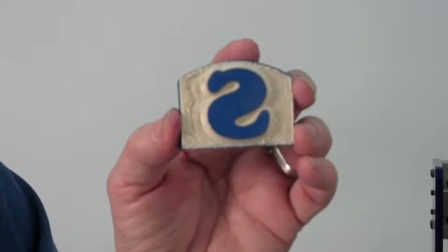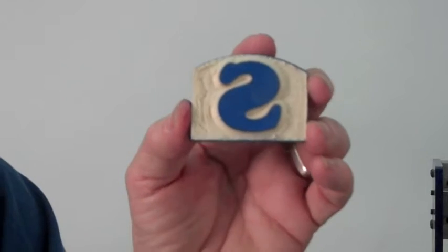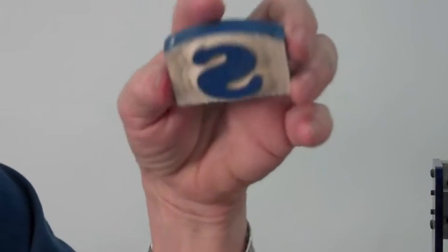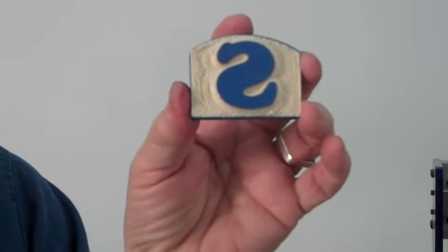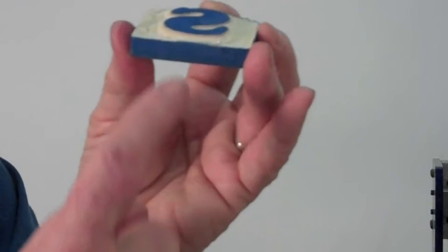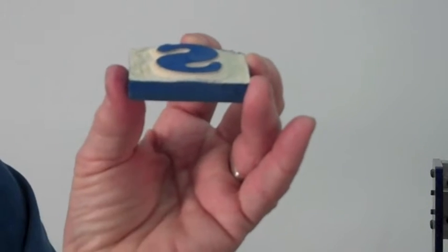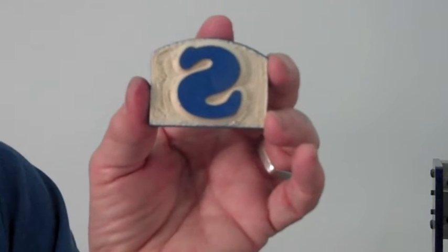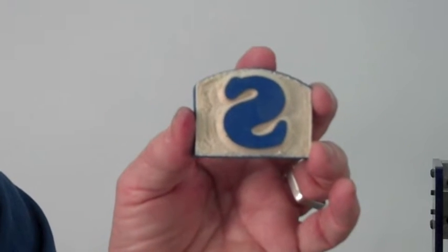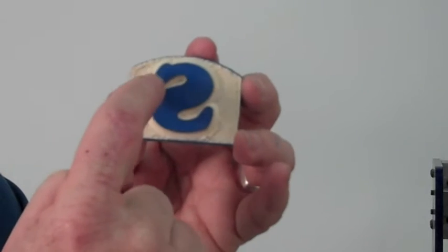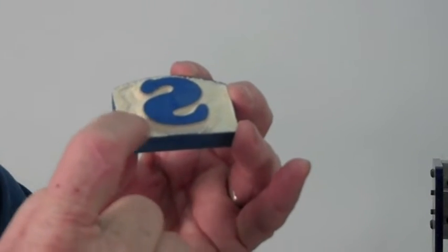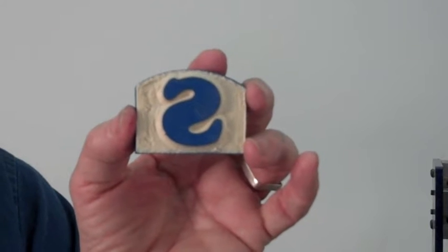So there are two things that I would like you to notice about this stamp. The first is that the S is reversed so that when you actually make the stamp, your S will be positive on the material that you're stamping. The second is that the S is raised up above the material. And because this is a subtractive process, we're machining material away as opposed to adding it, we can't add to the S, we have to machine the area behind the stamp so that your S ends up being above the material.